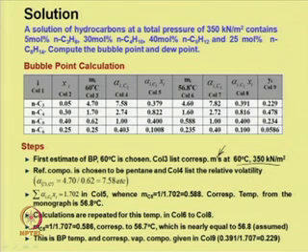So, we can see alpha C3 C5, the relative volatility between these two, is 4.70 divided by 0.62, which is around 7.53, and so on. If we know the distribution coefficients and the relations between the distribution coefficients and alpha, we can obtain the relative volatility for each component. And then we can add up the sum of alpha i C5 x i, which is given in column 5.